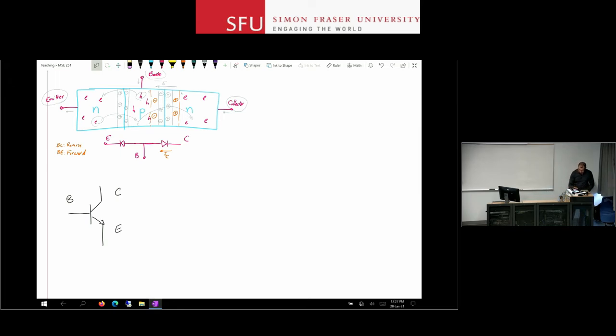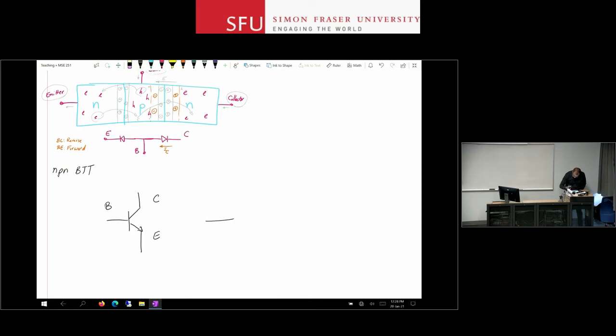Let's focus on this device. So this is an NPN bipolar junction transistor. And internally, I know inside this device what I have is a diode. So the base is the P here, N is on top, N is at the bottom. I know I have a diode in this direction between the base and collector region, and I have a diode in this direction between the base and emitter region. So this is collector, emitter, and base.